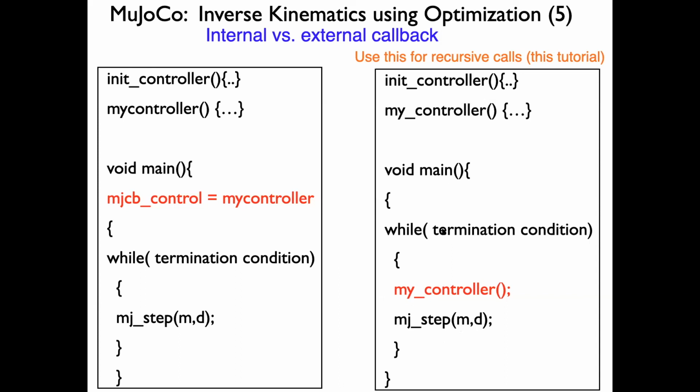When you are writing code for a robot, you typically are in the world on the right side. You basically compute the controls and then you send them to the robot, and in that time span, which could be 1 millisecond, 2 milliseconds, 3 milliseconds, it doesn't quite recompute the controller within that time step. So when you are using this code for a robot, what I did today is more realistic than what is on the left. The left side makes the function evaluations more accurate because they're internal. Here it's less accurate, but this is more realistic.